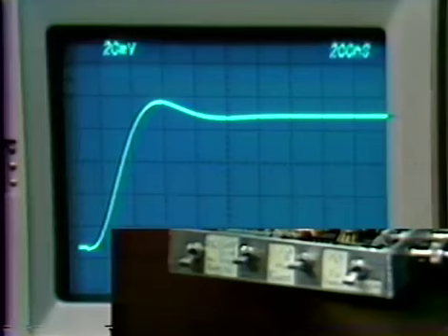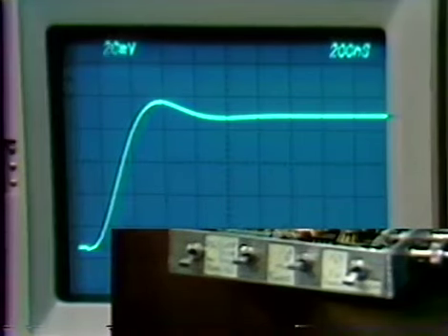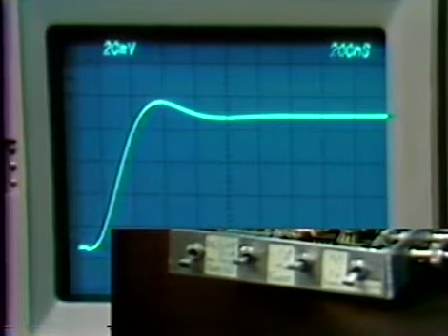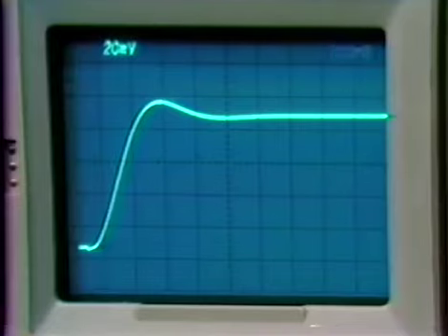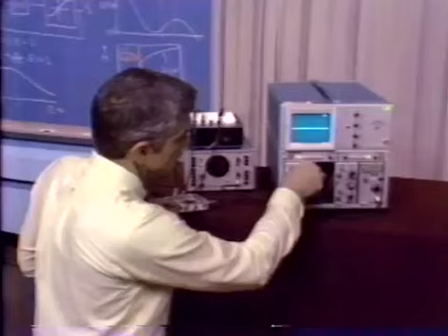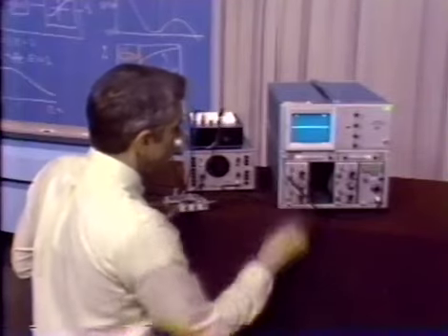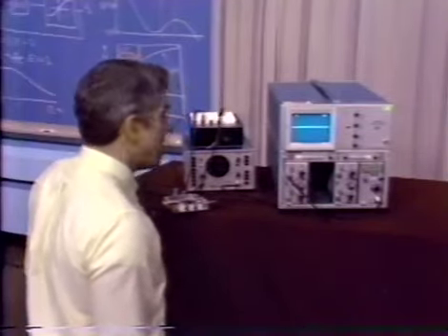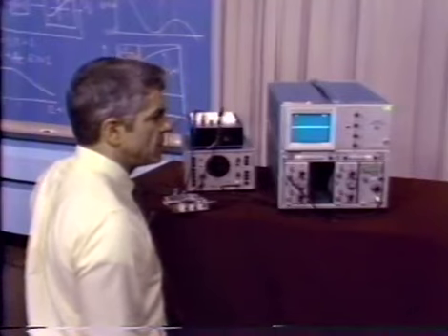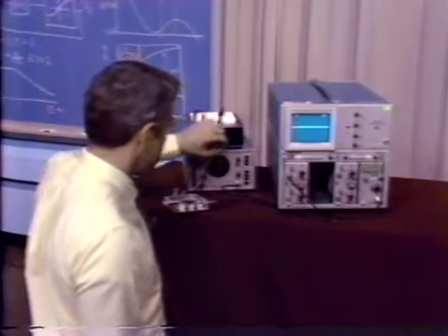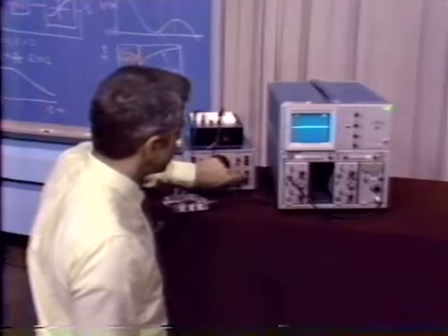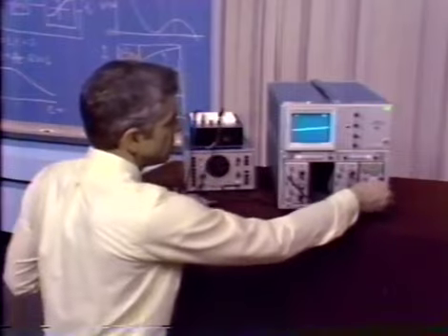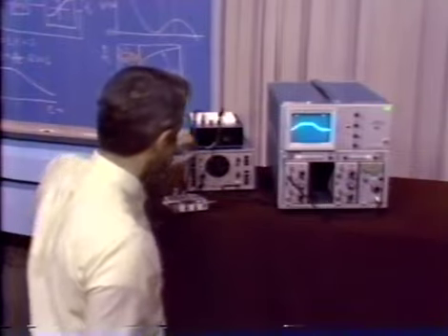But now let's look at what happens if we look at the large signal behavior of the amplifier. What I'm going to do now is simply up the amplitude of the input square wave that we're driving this with. Let me get to a more convenient scale. The amplifier at its output saturates at voltage levels a little bit in excess of plus or minus 10 volts. Let me apply a signal which actually never exceeds plus and minus 10 volts. We now have 1 over s compensation.